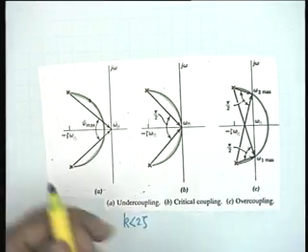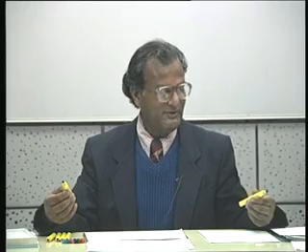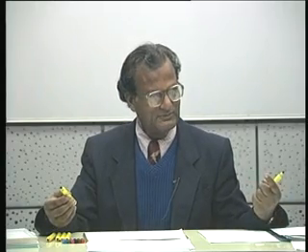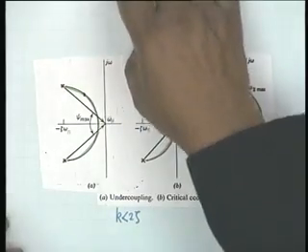Physically there are two coils which are brought close to each other to interact with each other. Suppose they are taken far apart so that k is 0. Obviously each tuned circuit will show its own behavior, and therefore there shall be only one maximum and two half power points. Agreed? So this is called undercoupling, and the extremum value of undercoupling is obviously k equal to 0. No coupling. Both tuned circuits behave in their original manner, they don't interact with each other.